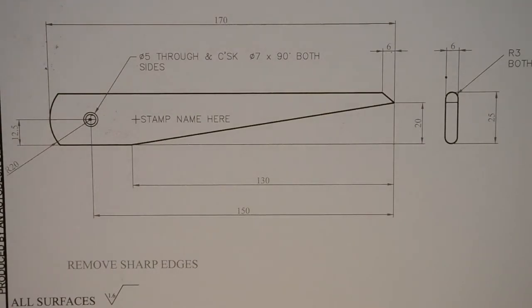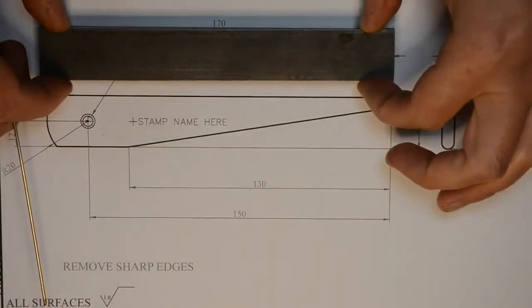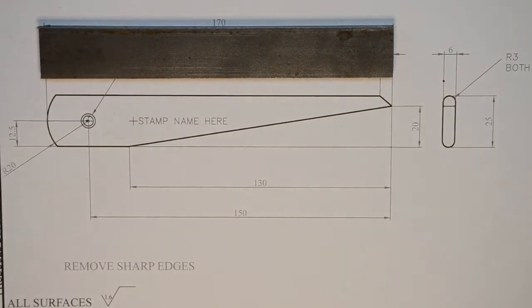Okay, let's look at datums. So we're always being asked about datums on our Q&A. Establishing a datum is one of the most important parts of making a start on producing a product from a drawing. And we tend to think of it in terms of what we're going to do with the piece of material.